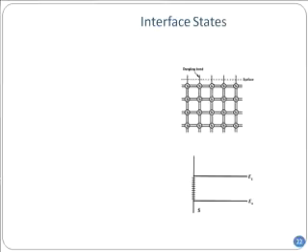And what happens, do you remember that we calculated how many atoms I have on a 1, 0, 0 surface, 1, 1, 1 surface, do you remember? Because those bonds are dangling, those bonds can capture electrons. So those will all come as surface states. Do you remember the surface state, surface recombination velocity and all? So this is exactly from that diagram. You will have a series of surface states because the crystal is no longer periodic. You're stopping it. As a result, you will have a series of dangling bonds which are not the solution of the periodic Schrodinger equation.